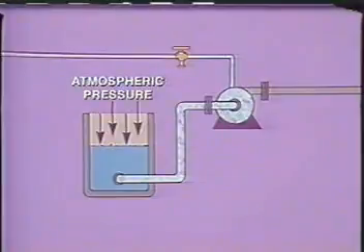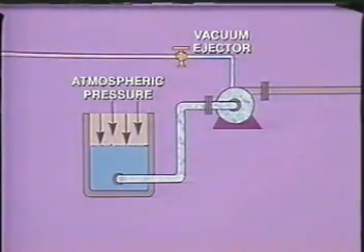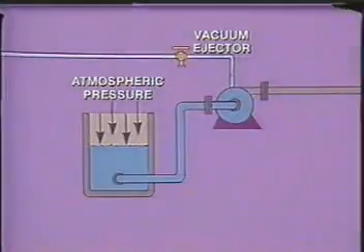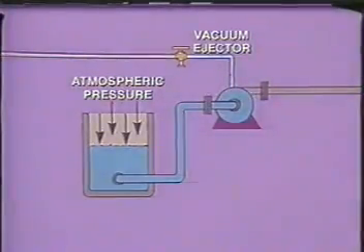If the pump takes its suction from below, the pump can be filled by some sort of vacuum-producing device. As the air or gas is removed from the casing, the liquid will enter as a result of atmospheric pressure. This is similar to drinking through a straw.